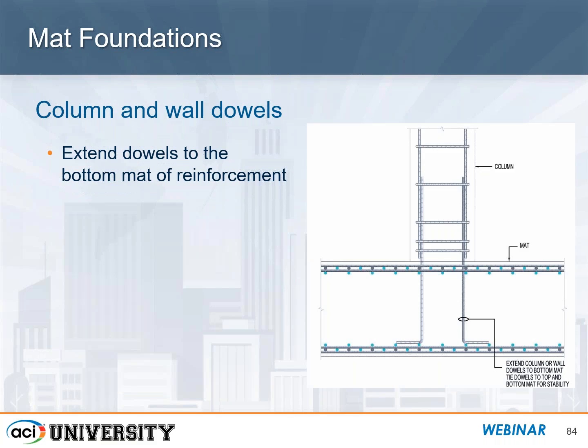Similar to what we have for footing, we want to extend the dowels from the supported column or wall directly onto the bottom mat of the reinforcement, tie down very carefully.